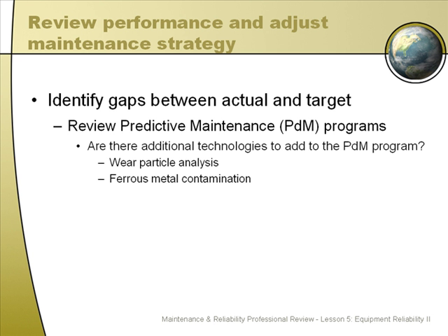Part of the lubricant analysis technique also includes wear particle analysis and checks for ferrous metal contamination in the lubricant. There are other additional technologies to add to your PDM program, and these subsets of the lubrication analysis program are very useful for identifying what's going on inside of a piece of equipment.